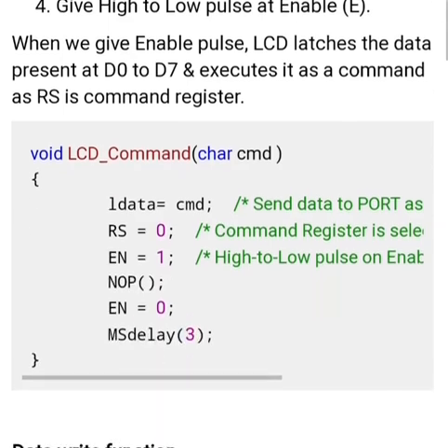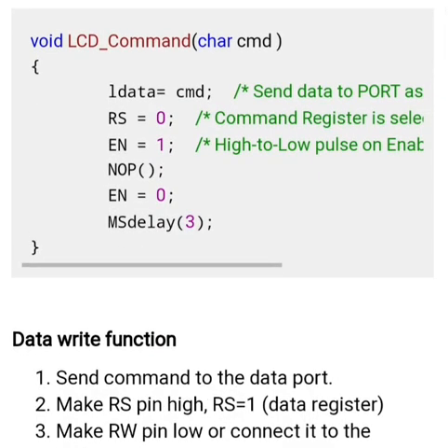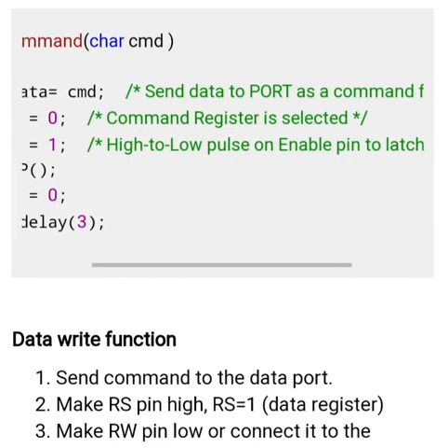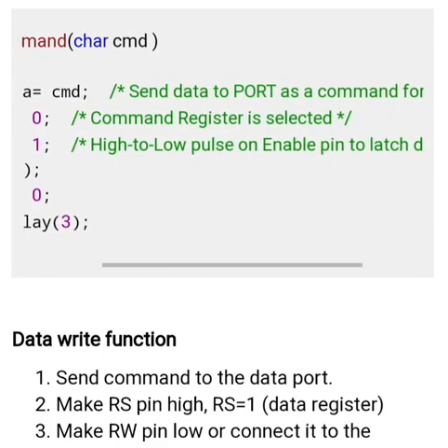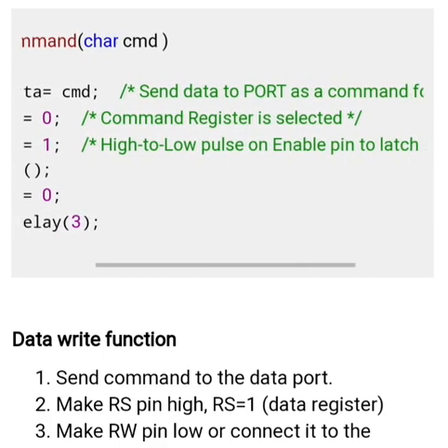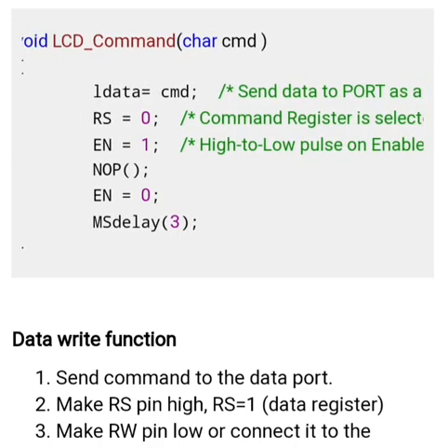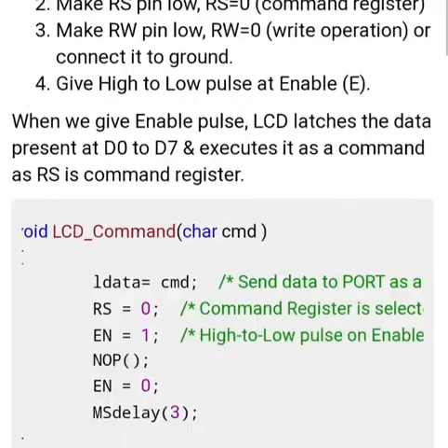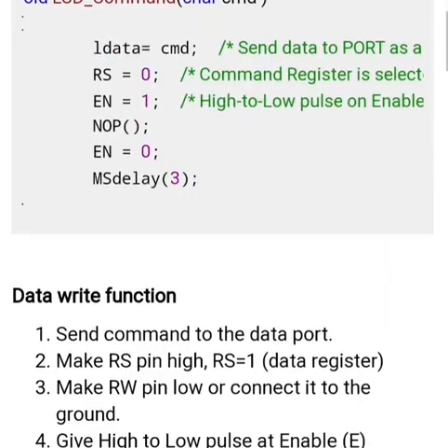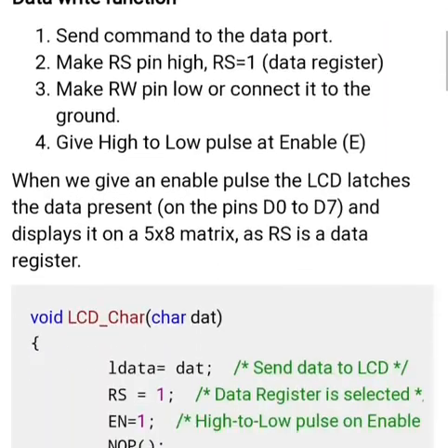So this is all about the command write function. First the data is sent to the port, the command register is selected, then a high to low pulse on the enable pin. So this is the command write function. Then the next is data write function.